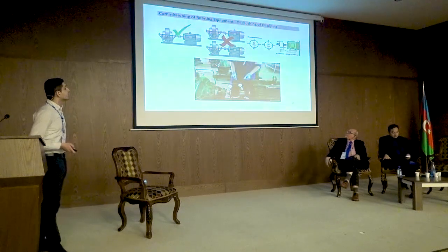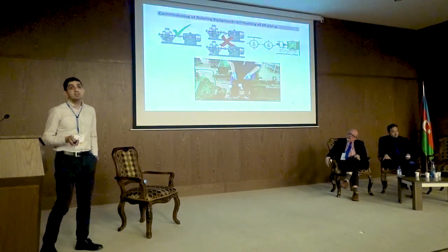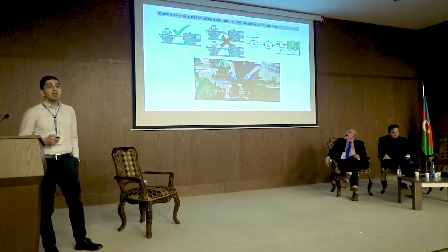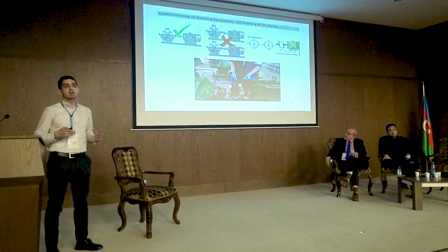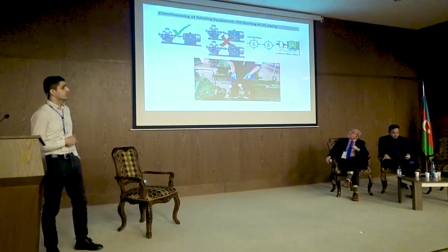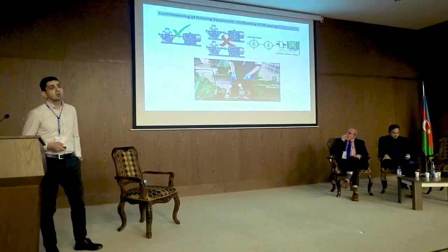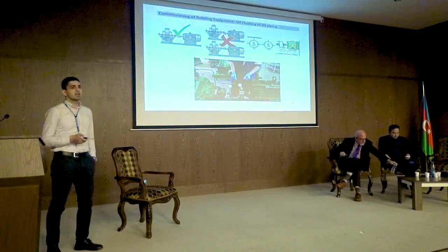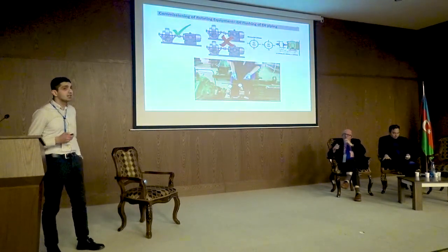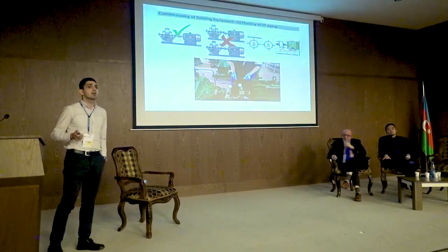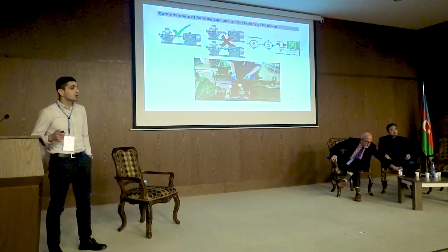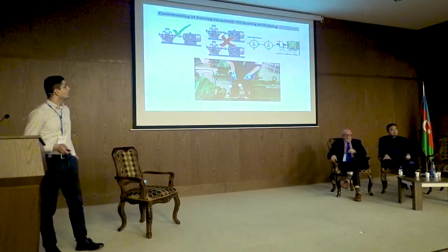So this is a typical alignment procedure that we are doing. Once we have installed the rotating machinery, the driver and the driven unit, we have to make sure that the driver and the driven unit are well aligned. So for a simple turbine, it can be a one day long procedure. But for a big machine, like a big centrifugal compressor driven by a steam turbine, it could take even months to make proper alignment, because we also have some other factors like piping and so on to be taken into account.